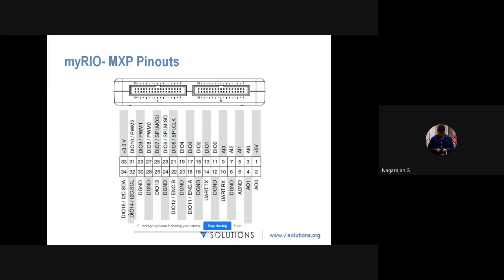You can see here I have something called UART TX, UART RX, in 14 and 10. So these two pins will support UART protocol, and if you see some pins they have mentioned as I2C, I2C dot SDA and SCL. So this is used for I2C based protocol data transfer. And then we have SPI.